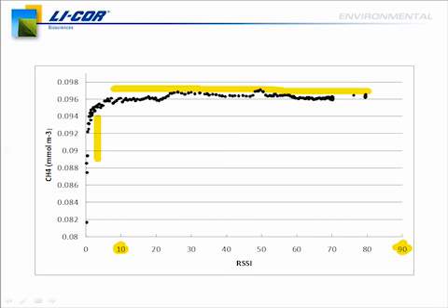But what we've seen in the field is that at a worst case, probably every 2 or 3 weeks you may have to go out to the site to clean off the mirrors, but more likely it would be 4 to 6 weeks between field visits. So thanks for your question.